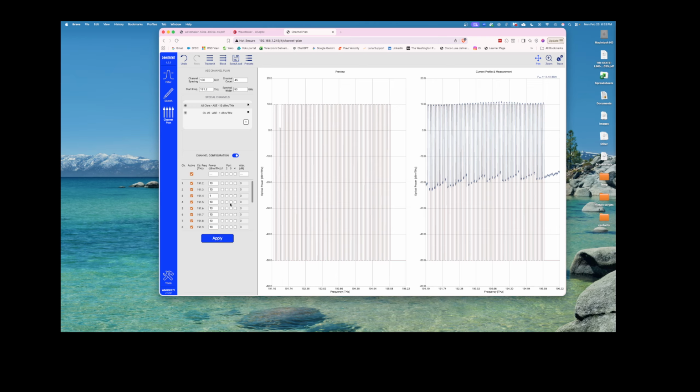And let's make this guy go down to 0 dBm. So that's channel 4. And let's say we drop channel 20 altogether. And then let's make channel 24 12 dBm. Hit apply, and it all comes through.